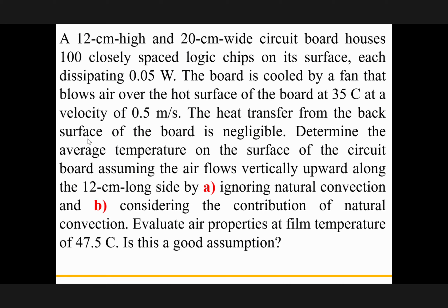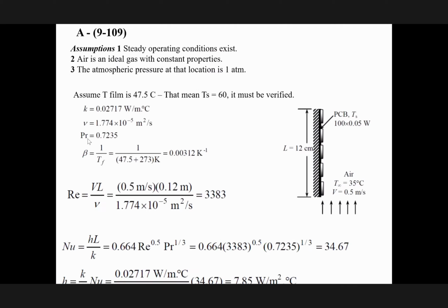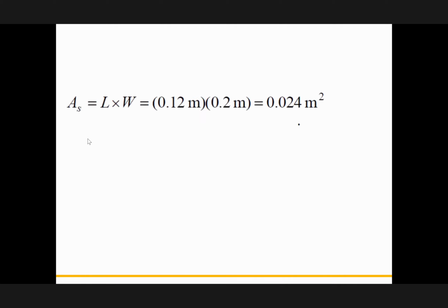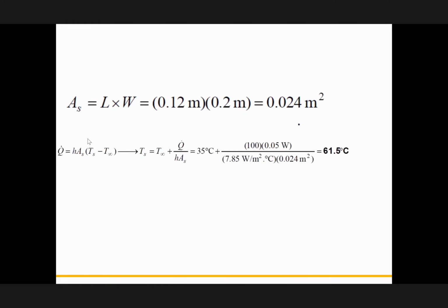Verification here is, now we look at the Grashof number, and we calculate the ratio of Grashof number to Reynolds number squared to see what range it is in. Is it less than 0.1 or more than 10 and so on? Therefore, by ignoring it, yes, we got some number and we solved the problem as forced convection heat loss from the plate, and we found the number is okay. And we say, well, that was a good assumption that we started with, 47.5.